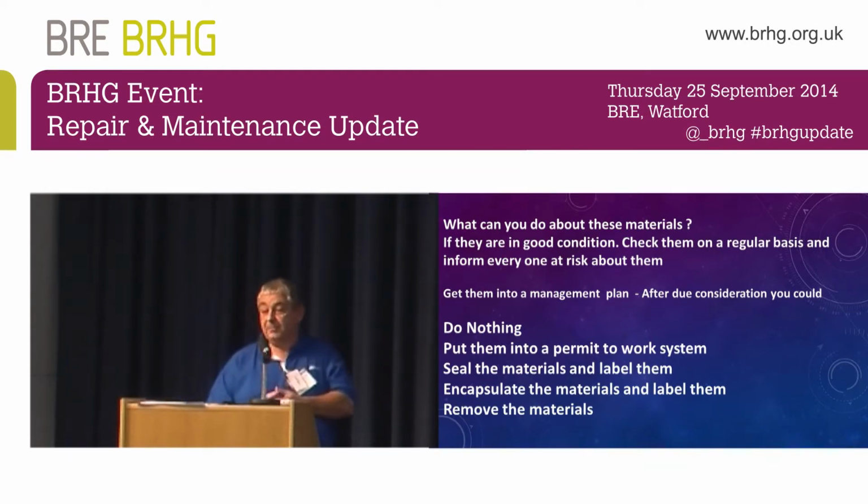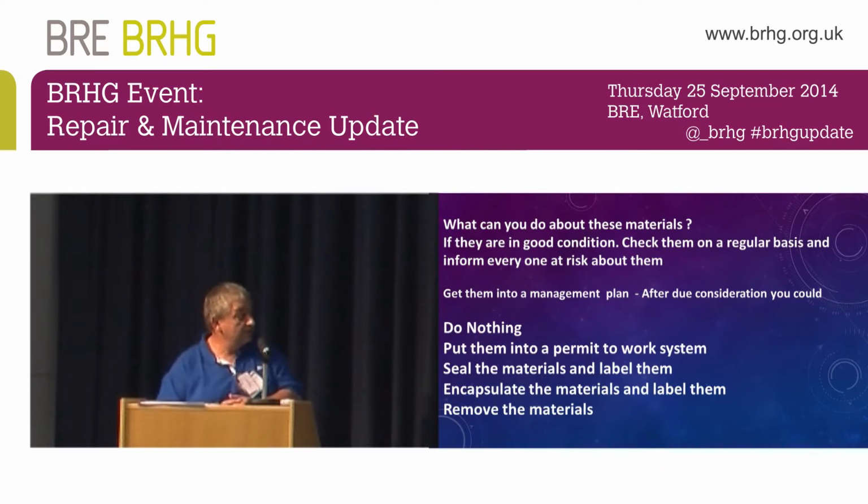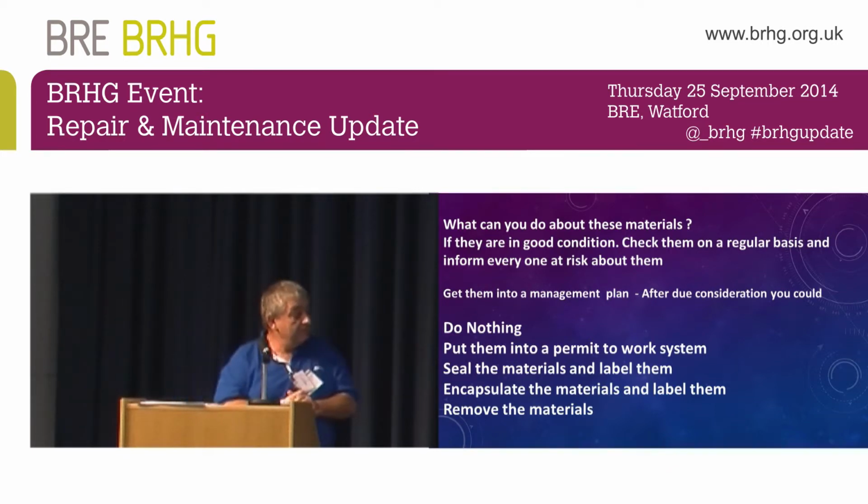Seal the materials and label them. It's certainly what we do with a lot of schools. They can't afford to remove these things. Just can't afford to do it. It's very, very expensive, asbestos removal work. But if you're not going to drill through them in the near future, seal them and label them.